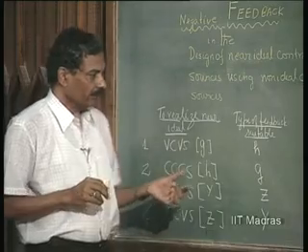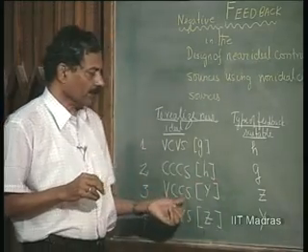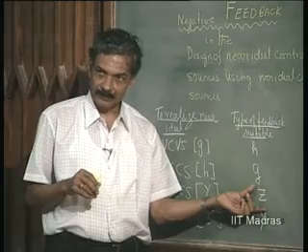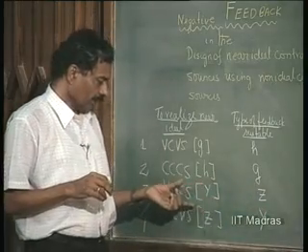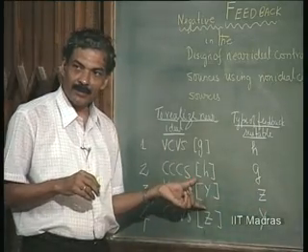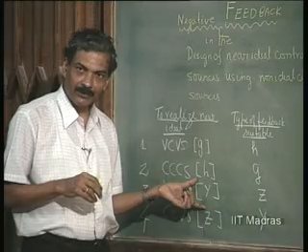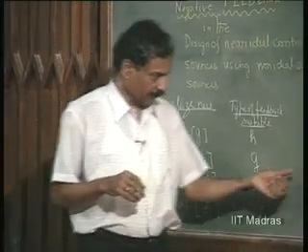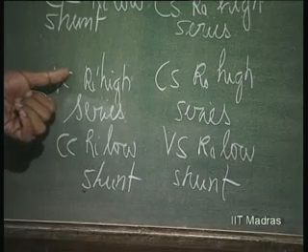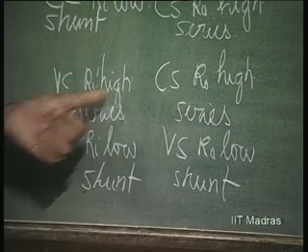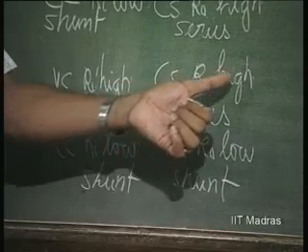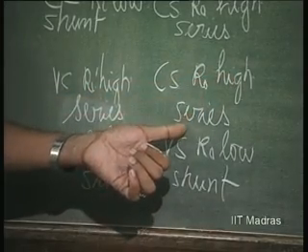Similarly, if you want to design a voltage controlled current source, the feedback that is to be adopted is Z feedback, the voltage controlled current source by itself ideally being expressed only in terms of the Y parameter. We have voltage controlled indicating R i high, so things are in series at the input, and current source being R naught high, things are again in series at the output.